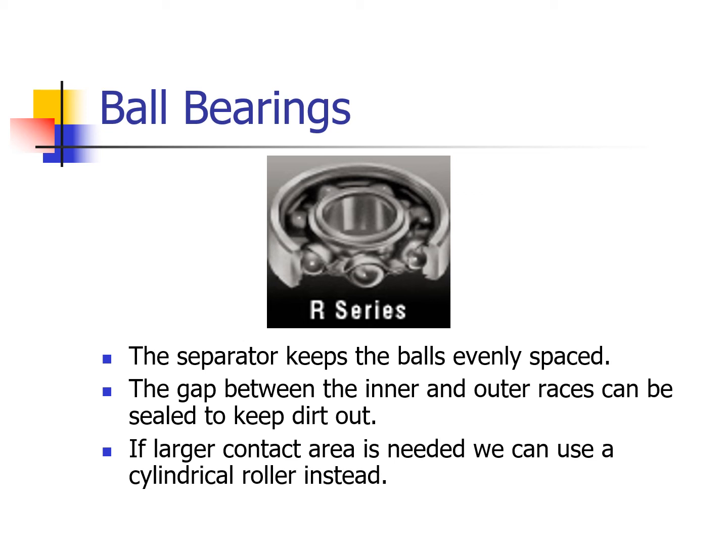If you look at that picture, between the inner and the outer race, there's a gap where you could see the ball bearings in there. Sometimes that could be sealed, and not sealed, to keep the dirt out. In certain applications, you want to make sure that dirt does not get inside, because the dirt will make the bearings wear out much faster, right? So if you hear the term sealed bearings, that's what they mean. That means that there's a seal in there so that dirt will not get in there and damage the races.